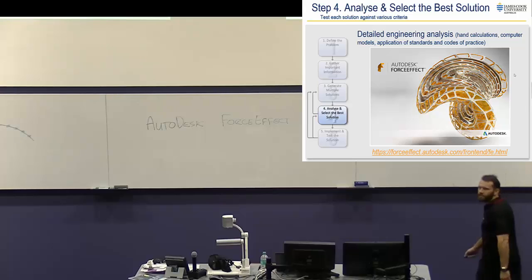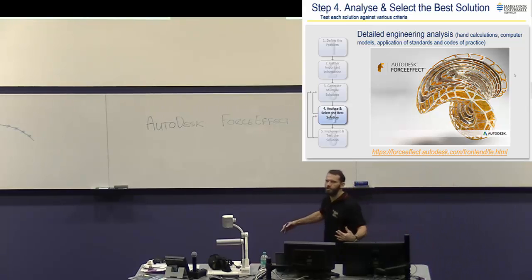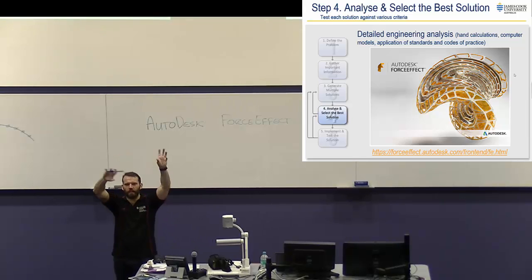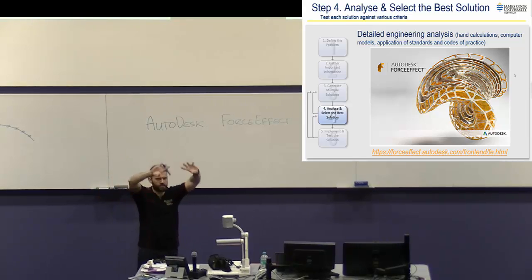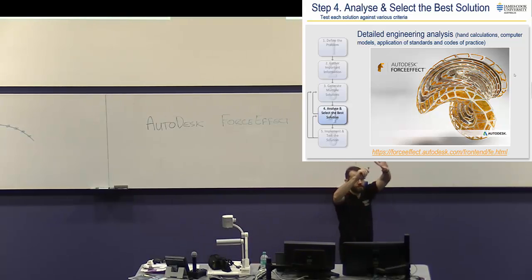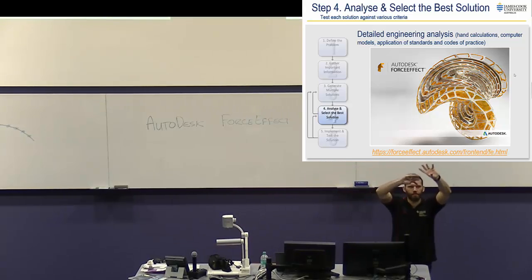The other thing you can use in this software is construction geometry. Some of you might have been seeing that as you're drawing it, it gets wobbly and then you set up dimensions and things move. If you want, you can set up construction geometry and put dimensions on it, or you can set members up and put a dimension on it and then delete it before you actually do the analysis.